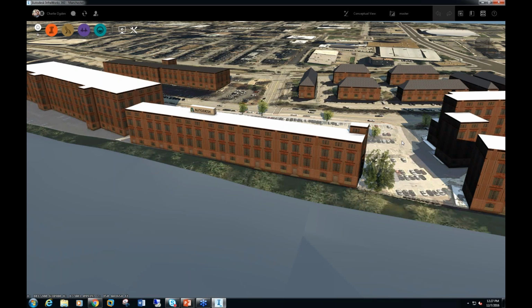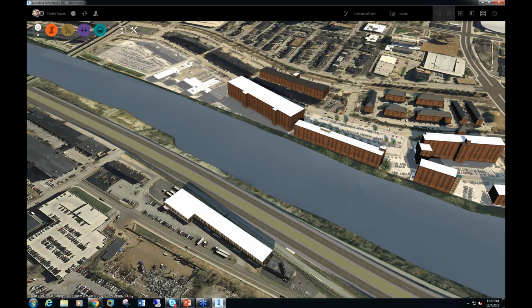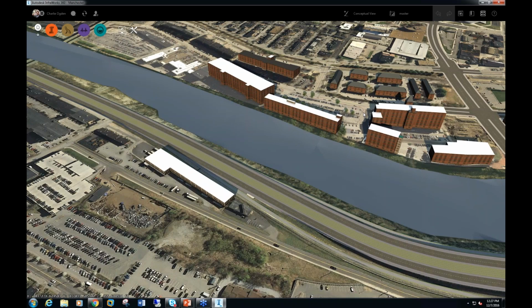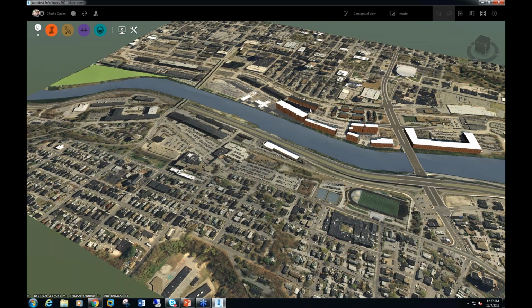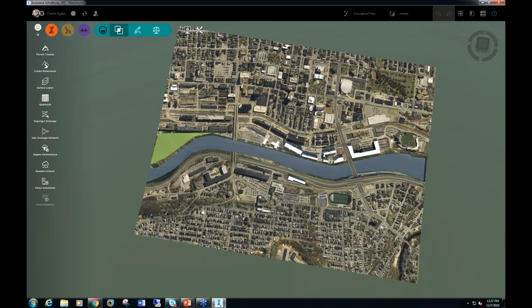So here's my InfraWorks model. You can see the office building and the river that flows next to it. And on the drainage toolbar, under analysis, you'll find when you have the RiverFlow2D plugin installed, these two commands down at the bottom, flood simulation and this flood snapshot. So flood simulation will let me define my simulation area, set up the configuration.